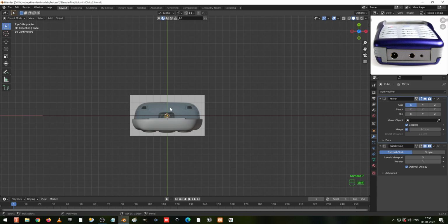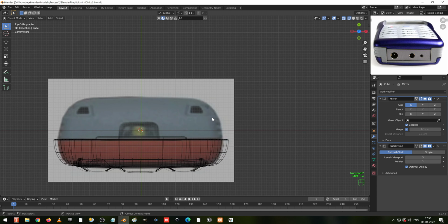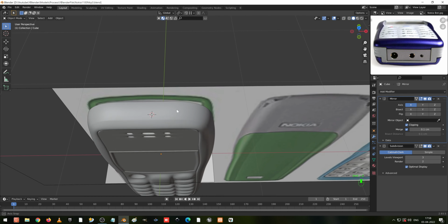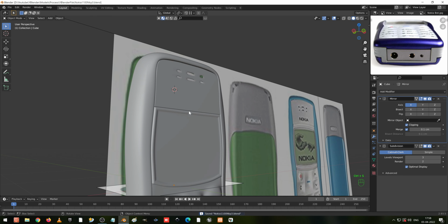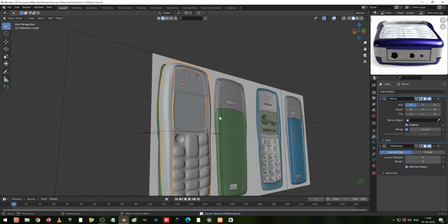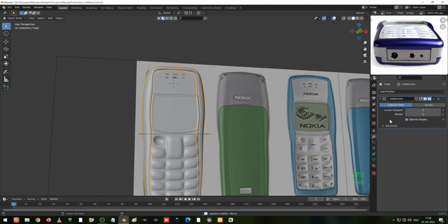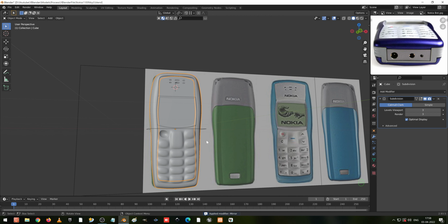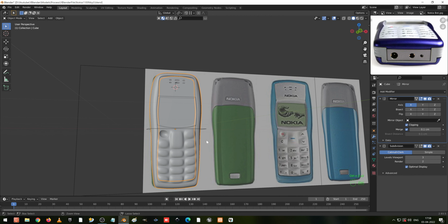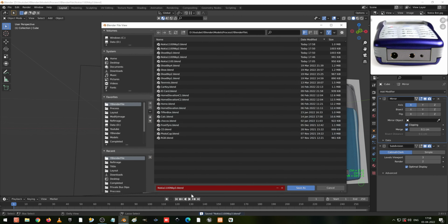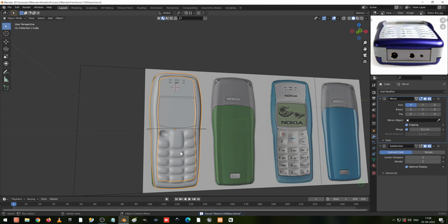Now go to the top and shift Z. Here we have a back panel, that plastic paste which is going to come. Okay, let me see it later in the next video. Now I save the file. We have to start doing the unwrapping. So this panel does not matter. I apply a mirror and subdivision. Before doing unwrap, I save it. I make a new backup, because it is always best to keep a backup.